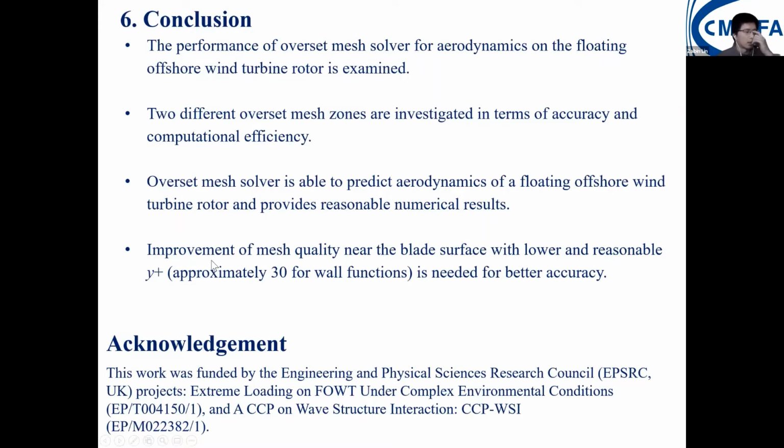And next step, we're going to improve the mesh quality near the blade surface with a low and reasonable Y+. Approximately 30 for the wall functions is a requirement for the wall functions and is needed for better accuracy.